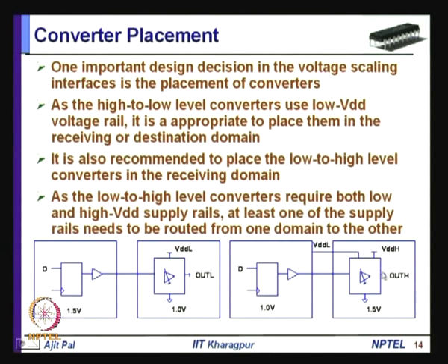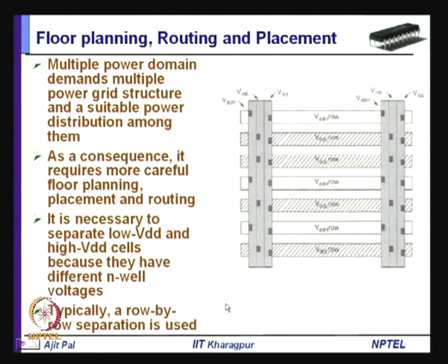This particular level converter can be placed here or here, but it is beneficial to place it in the low voltage domain, because this reduces some of the timing problems. But VDDL has to be taken from the low voltage domain to the high voltage domain area. So, this will increase the routing area, and obviously your cost of routing will increase. So, this is the challenge of placement of level converters.